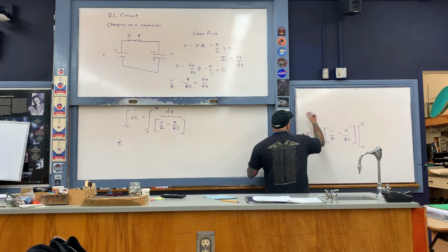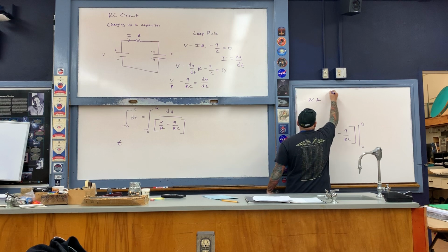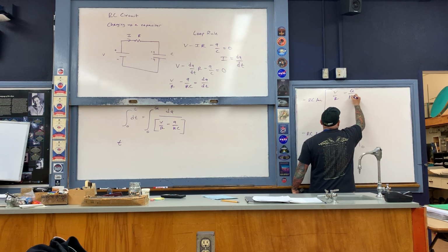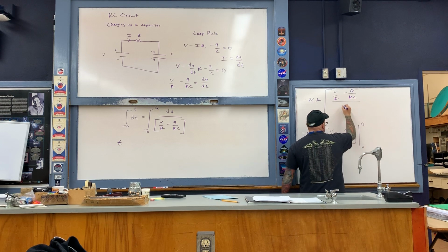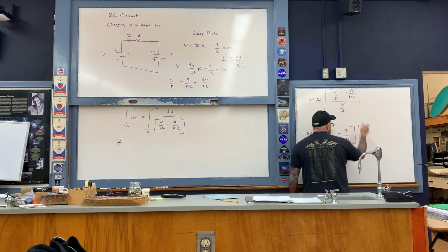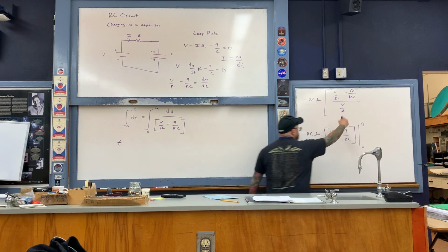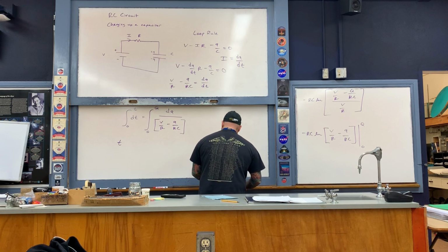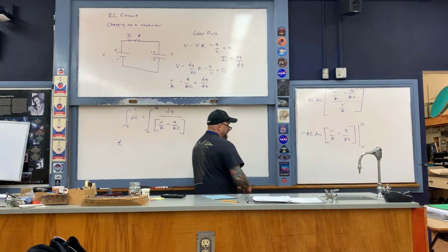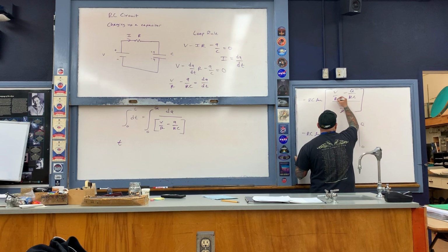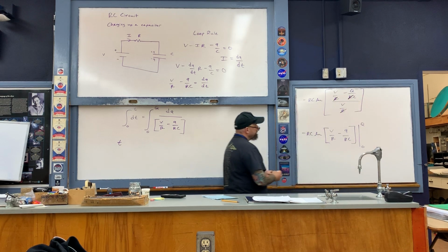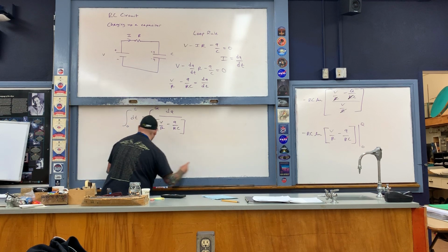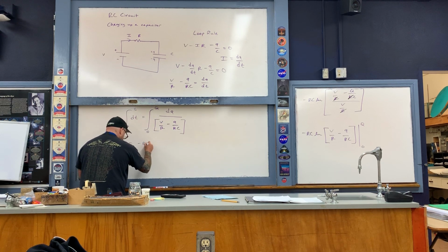Okay, plug in the limits of integration here, and when I do, I obtain this. Let's see, V over R minus capital Q over RC, and then just divided by V over R when we plug 0 into the natural logarithm, like so. Close the brackets. Okay, I can go ahead and cancel out an R there in each term, like so. Okay, and now then, therefore, the right-hand side of the expression over here on this board is the following.